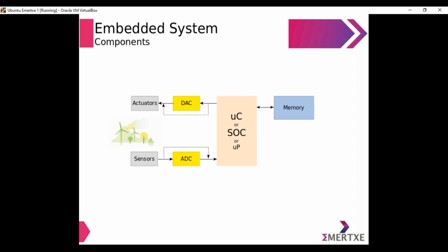So sensors sense the signal. Okay, it's like a closed loop. The sensor senses the signal. It gives you an analog value, which is further given to the ADC to convert it into a digital value. That digital value will be taken by your microcontroller. After your microcontroller takes that digital value, it makes some comparison, and according to that, it makes a decision to take the action with respect to the actuator. So they are output giving devices. So actuators are analog in nature. Some of the actuators will be analog in nature.